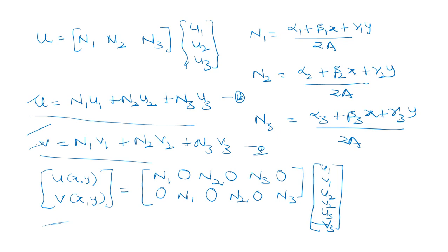Okay, these are the displacements of this CST element. Some others might write it as delta. Already I told you, delta means at any point the displacement is equal to its shape functions multiplied with its displacement components.